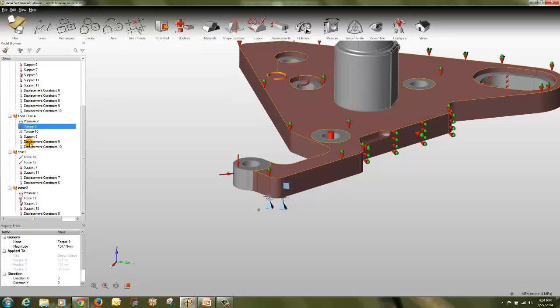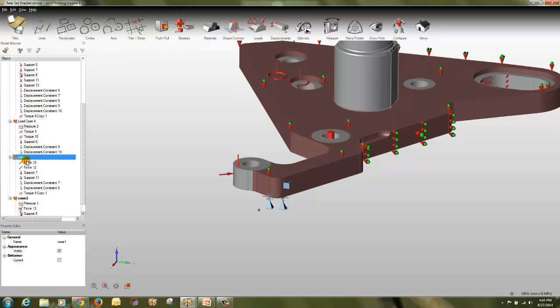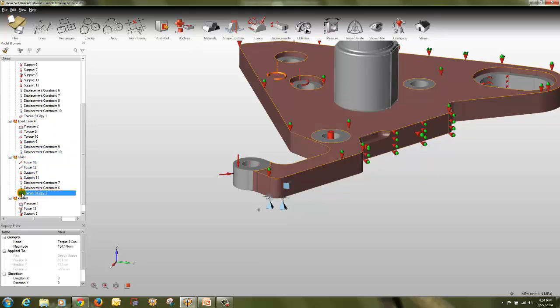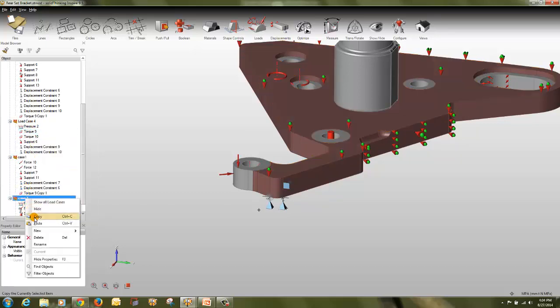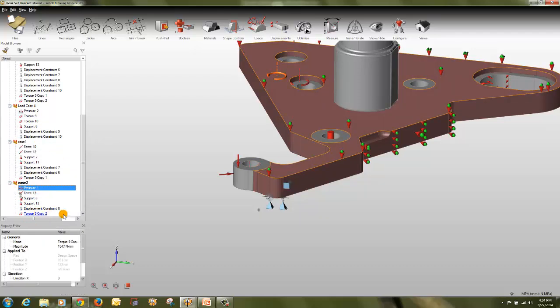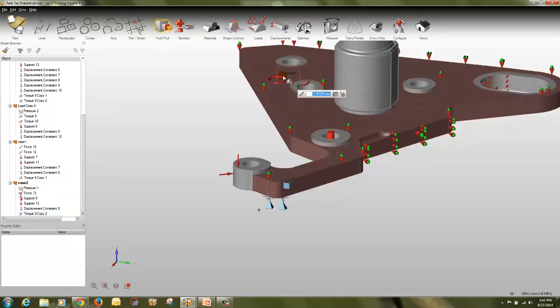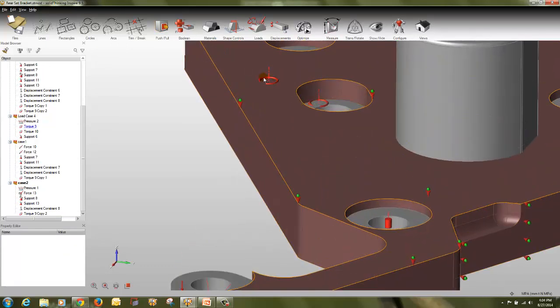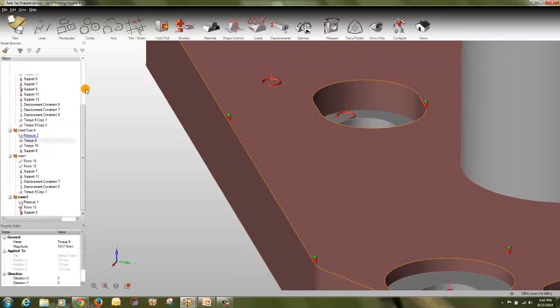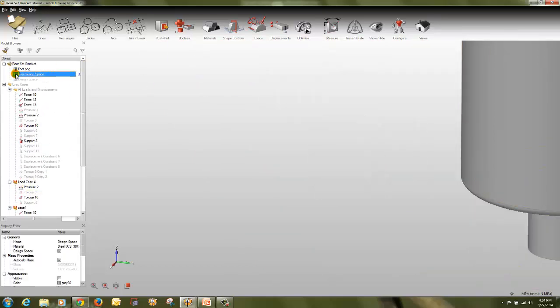And you can have a copy paste. So copy in this, paste. So you will have a torque constraint here. A torque constraint can be applied twice. So just copy and here click and paste. So you can have a torque here also. So we have a torque in 3 different load cases. Why did I copy paste it? For this case, let's suppose I want a torque to be in some other direction. So let's off this.